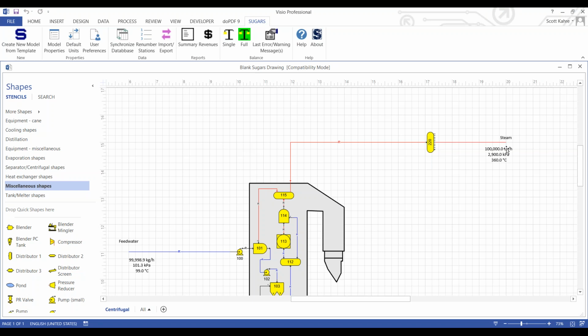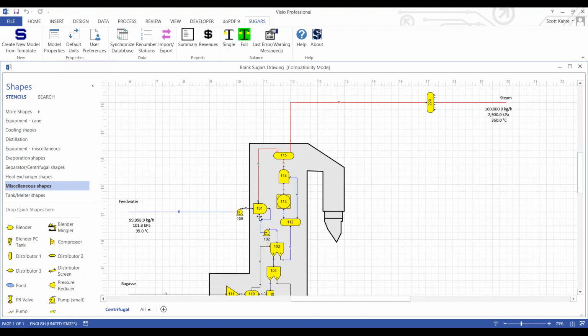And so what you can see here is that now, because we asked for 100,000 kilograms an hour of steam demand in this header, the steam and all the feed water flows are now required flows back through the boiler, and the feed water is a required flow. And of course, it's within tolerance the same amount, not perfectly exactly, but that's within the balanced tolerance.